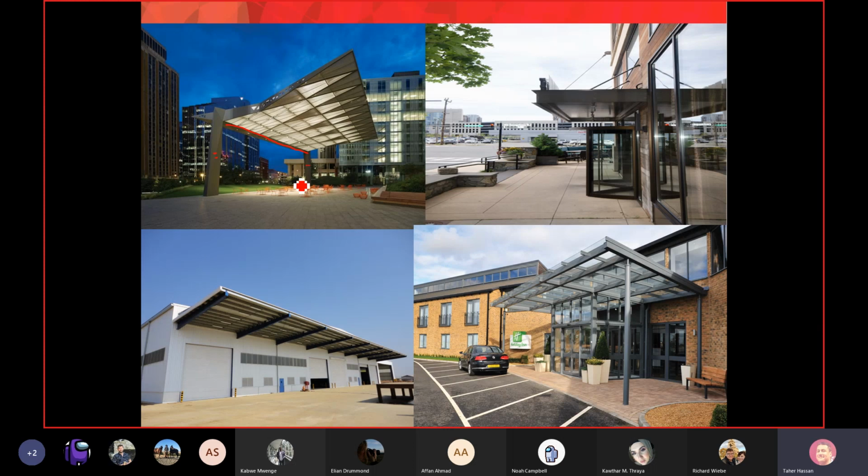Do you think this beam would have torsion? Yes, it has. Look at the canopy. Under gravity load the canopy will try to go down, and it will cause a twist around this beam here. So this beam will be in torsion.